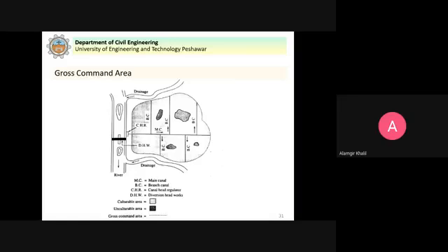So you can see here we have this river flowing. Then we have these drainages that drain into the river. From this river we have the diversion head work that we will study in detail in the coming lectures. We raise the water level, and then we have the canal head regulator that regulates the flow of water into the canal.